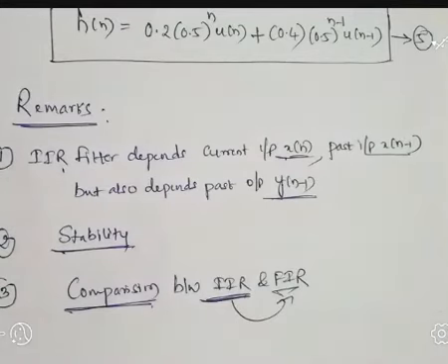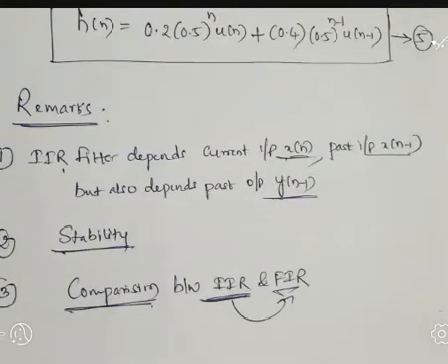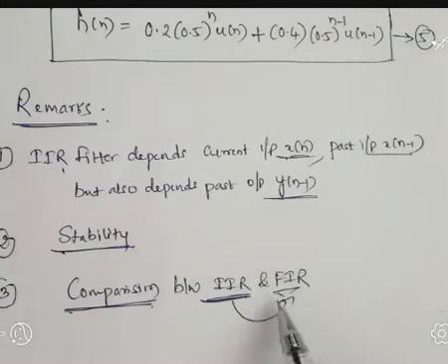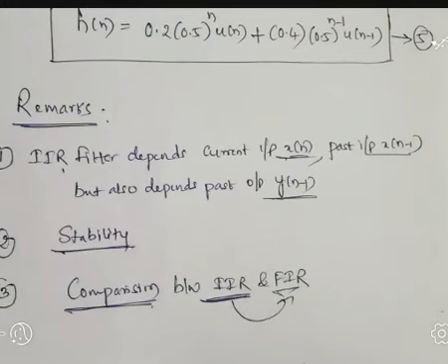Hence, the IIR filter is preferred when a small filter size is called for, but the application does not require a linear phase. Comparing with the FIR filter, it offers a much smaller filter size. Hence, the filter operation requires a fewer number of computations. It is the advantage compared with the FIR filter.